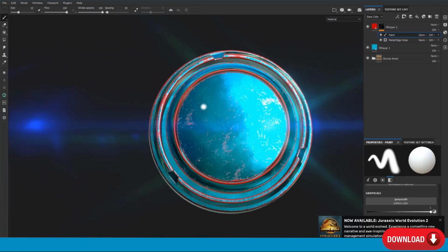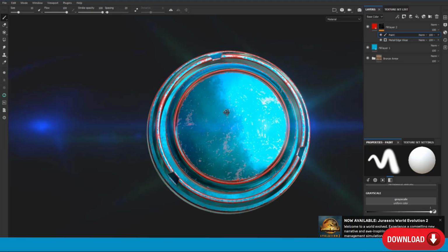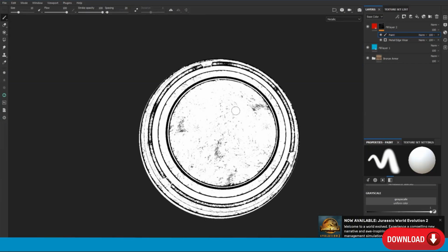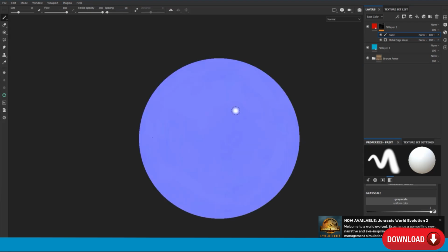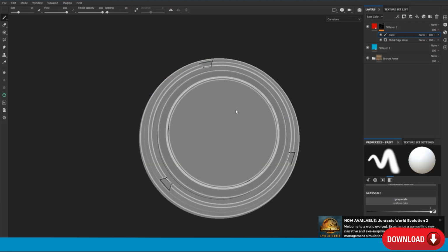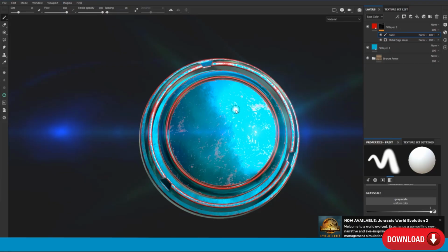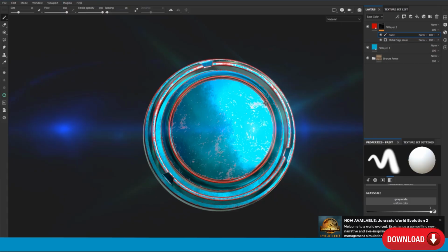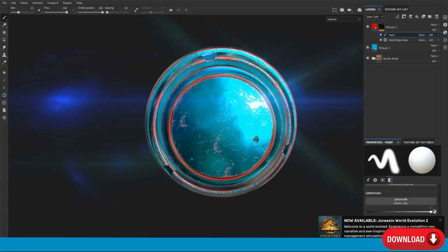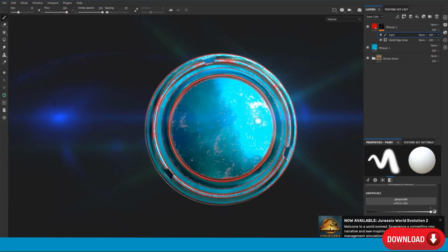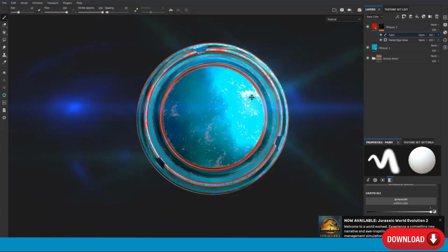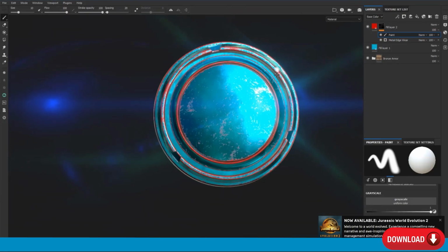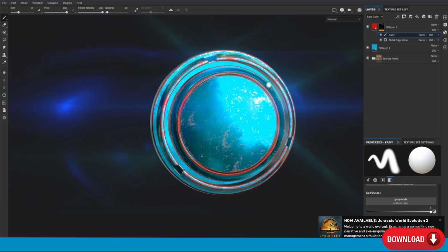Before we do that, let's recap something. We are changing the channels of our models. M for material again, and press Tab to fill your screen with the big interface. Alt left mouse button and Alt middle mouse button to pan, and right mouse button to rotate. These basic interface keys you have to learn.